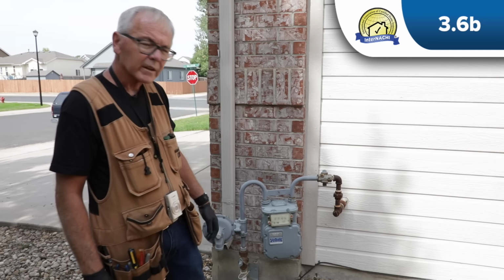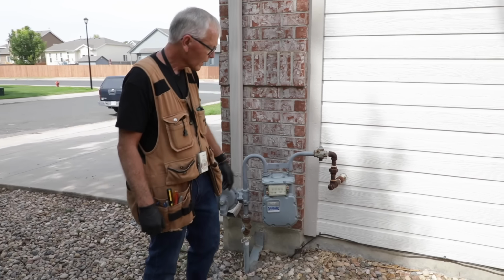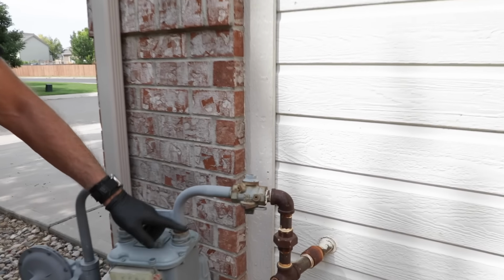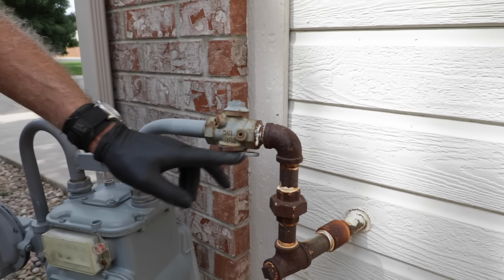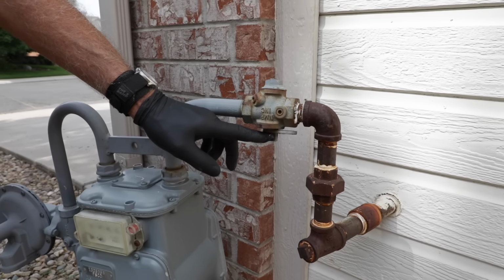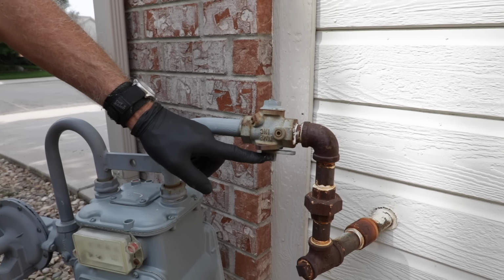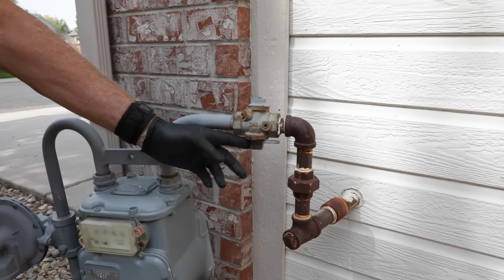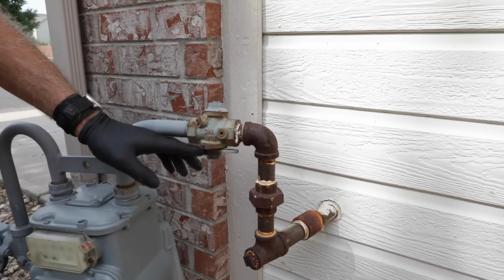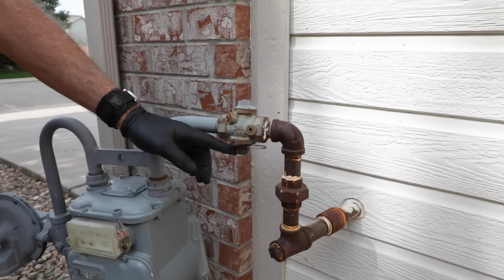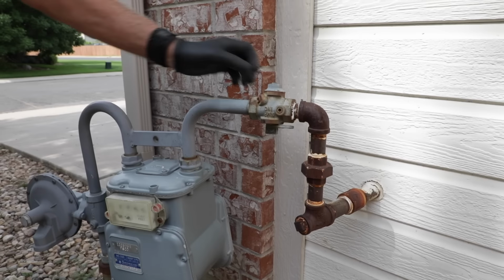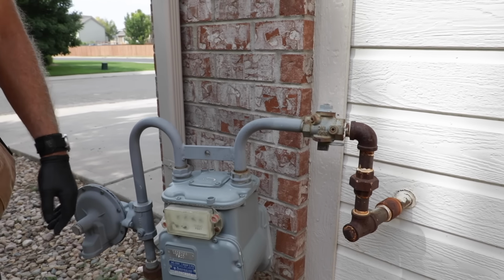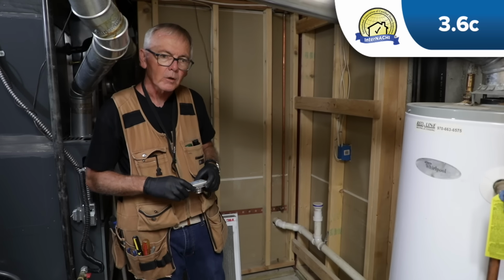Okay, now we're going to inspect the main fuel supply shutoff valve. We're going to have to go outside by the gas meter to take a look at this. And over here to the right of the gas meter is a valve that could be used to shut the gas source off to the inside of the house. And this is on the outside of the house. It looks to be in good shape. It's a little rusty, but typically they all get a little rusty from being outside. It looks like it's in good shape, and we don't have any gas leaks here because I can't smell any gas, so I think we're good.